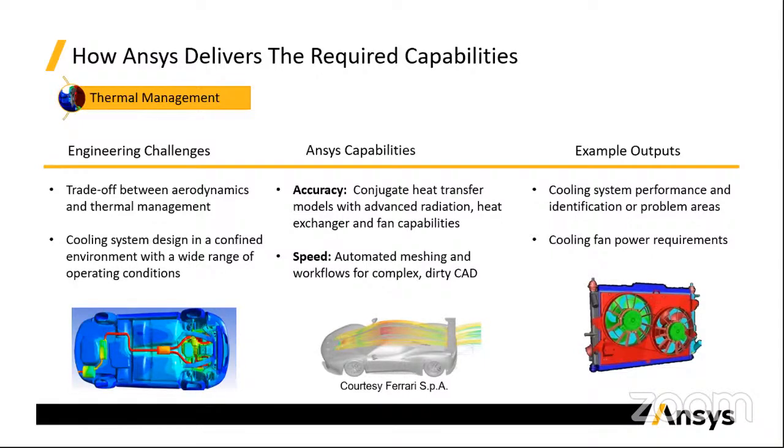So whenever we are talking about vehicles, there's a trade-off between aerodynamics and thermal management, right? You need to select a cooling package for your machine that will provide sufficient cooling to ensure that the heat that is being transferred from the energy sources, say, for example, the engine, doesn't overheat the components around the heat source.